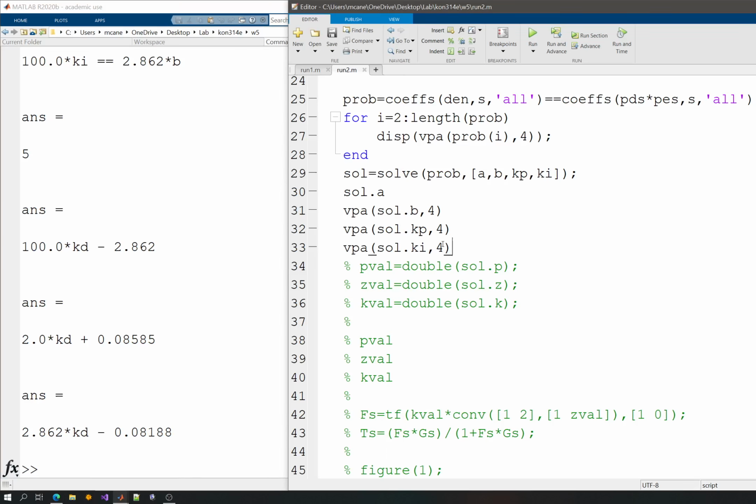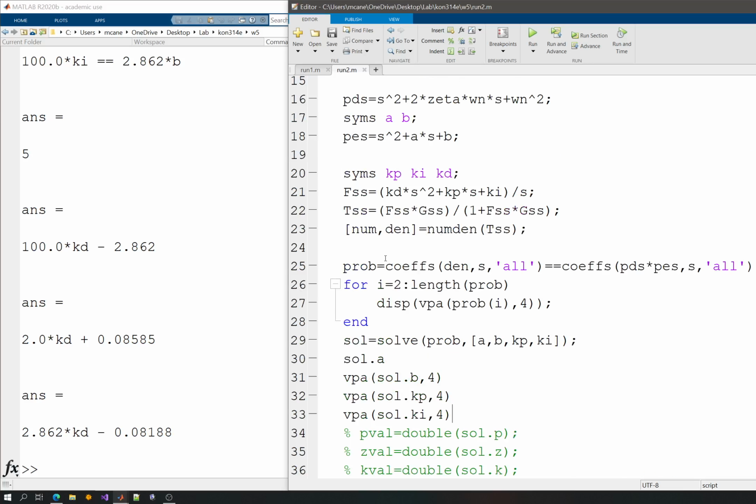And most of the time, if you don't want adverse effects, you should look at this numerator, and you can say that KD, KP, and KI most of the time probably should be positive, since for the same fact that A and B are positive, this should give me a stable pole pair, or a stable root pair, or zeros that are on the left half plane, since I don't want to have zeros on the right half plane.